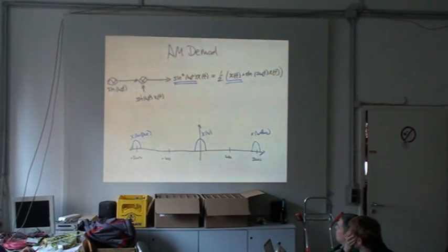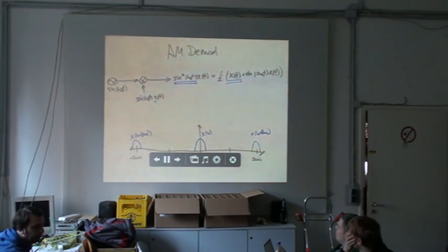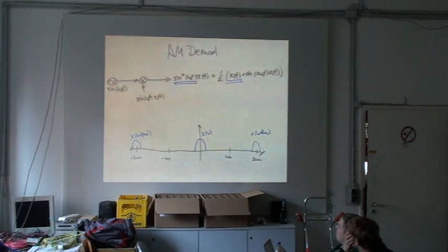So how do you demodulate amplitude? How do you demod AM? Funny enough, the demodulator for amplitude modulation looks just like the modulator. You have a sine wave carrier. Your input signal here is going to be multiplied by some sine wave carrier. And what you get out is some sine squared function times the original information signal.